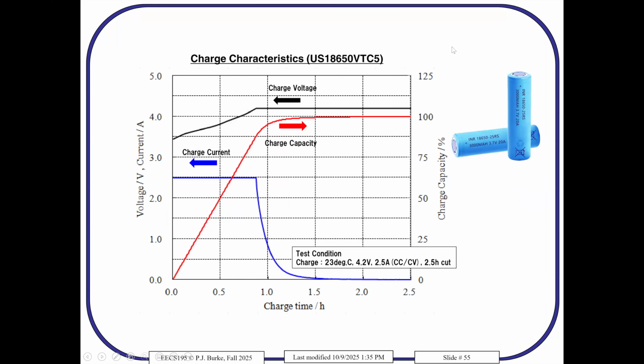Okay, so now how do you charge them? Because I want to do the demo charging. To charge the battery, as I showed you, it has to be done properly for safety reasons. You push current through with a charge circuit, but you don't push it all at once. If you push the current through too fast, you'll create a fire. And if you charge it up to too high of a voltage, you'll create a fire. So it's very important not to charge it too fast, and not to charge it to too high of a voltage.